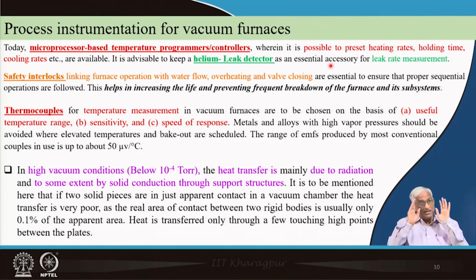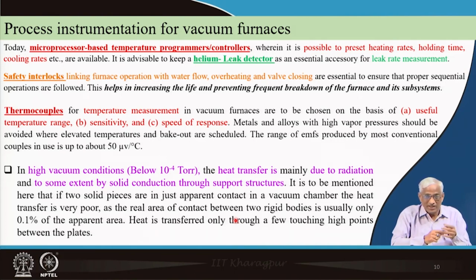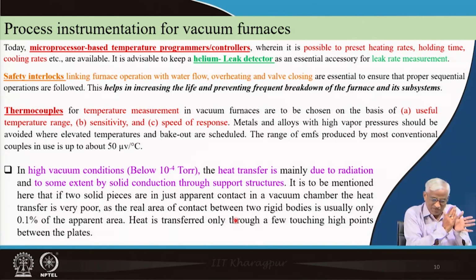And in vacuum some other important thing takes place, that I am telling you here. Whenever it is sandwiched, or heating, or shielding, or even if the thermocouple is stuck, if it is not properly stuck with enough force with nut and bolt, there may be a vacuum gap. At atmospheric pressure we do not see this, I will get the same feeling if I touch some heater, but in vacuum if there is a fine vacuum gap, there can be a 100 degrees error in the measurement. This may be 400 and the thermocouple is here, because of some thermal expansion or some loosening, it got a little loosened. It will measure 400 as 300.